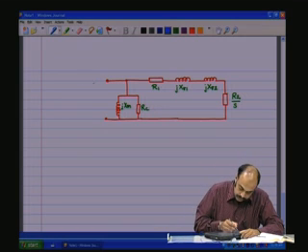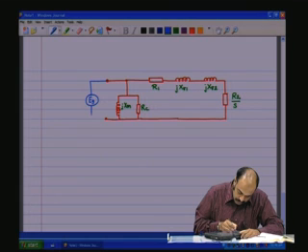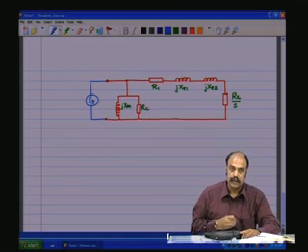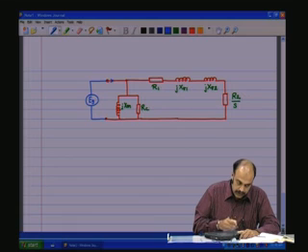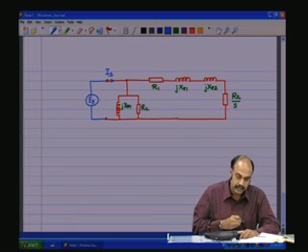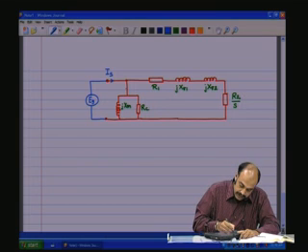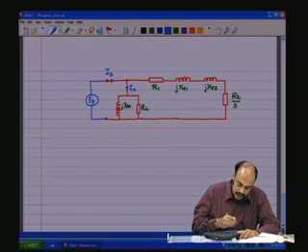And we connect the source, effective value, let's say this is EG, which is from the generator. It is connected like that. This current is the stator current, and we call that one IS. Out of this IS, the stator current, some portion goes for the magnetizing component I0.